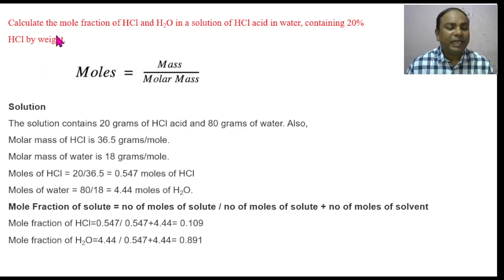In this way, you can convert a percent solution into mole fraction, or mole fraction into percent solution. You must be in a position to interrelate or convert each of the given terms as per convenience, because in a problem, suppose two streams are entering a unit process, and the quantity of each stream is given in a different unit.